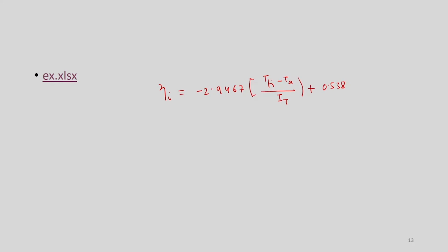Now, also we know the expression for eta I when we use Hottel-Whillier-Bliss equation. So, this FR AP by AC is tau alpha average minus UL, then TFI minus TA divided by IT.